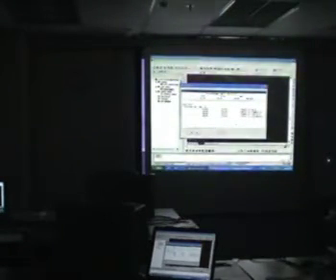So you can do a comparison between the grid method, composite method, area method, and the post model method. This is the cut volume, fill volume, net volume. F indicates an excess of fill. You can see the values are more or less the same, maybe the grid is just a little bit out. The other three are about the same. By using these different methods, you can at least be sure that the values you have are correct, you can compare the values.